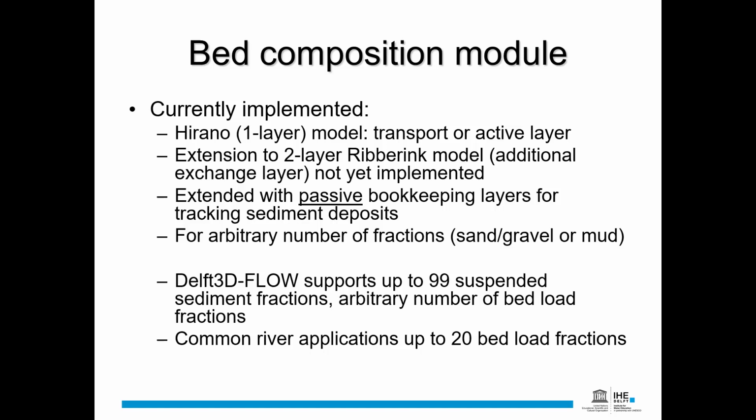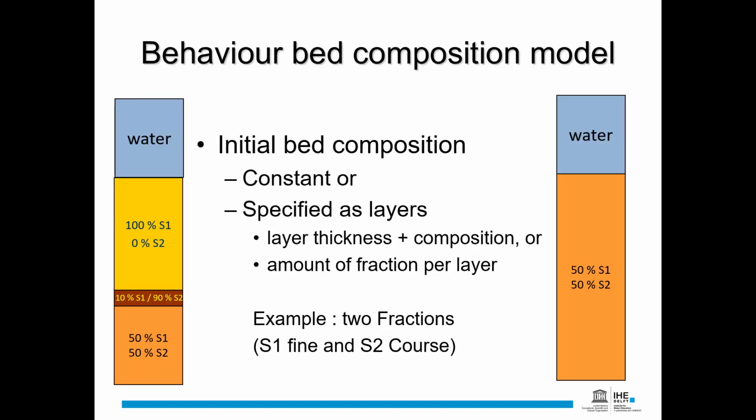Usually in a river application, we can use up to 20 bed load fractions. And in coast, we have used like 5, 6 different fractions based on the data that we have. But how does this model work? Imagine that we have a column of water and soil. So water, of course, is what we use the hydrodynamic model to calculate.